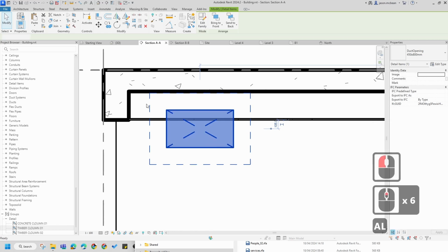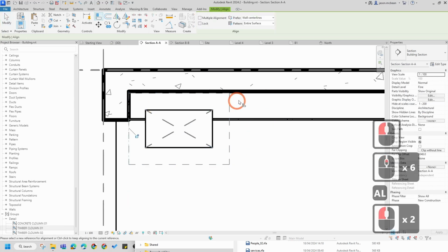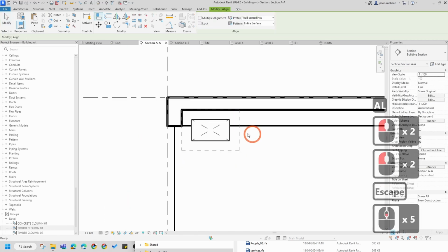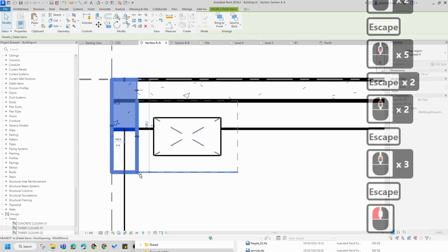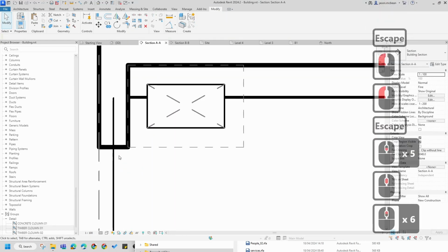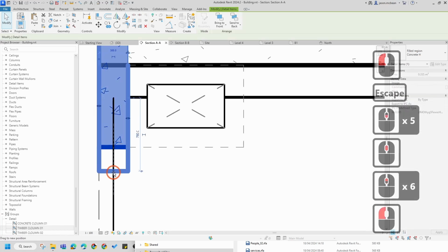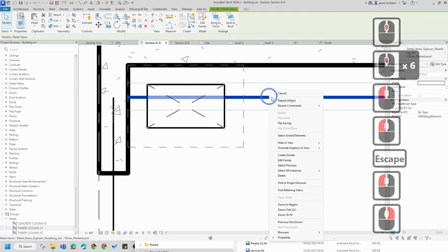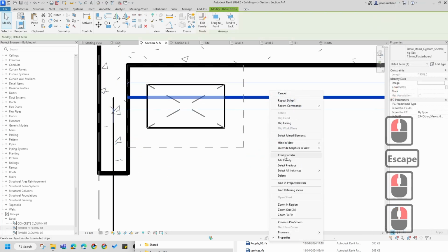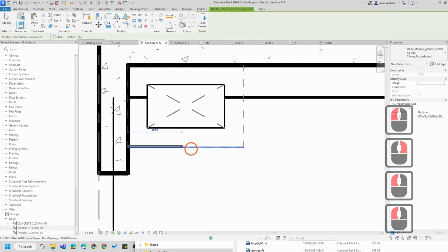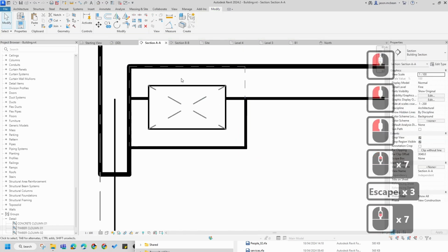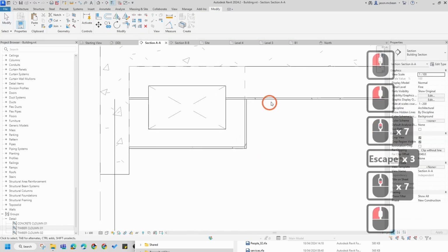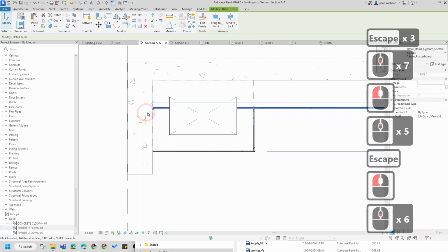So I can go align that to there, align that to there. I've got a duct here, for example, so maybe this downstand beam might have to get thicker, for example, or it might have to come down even more. Create similar. You can use this command to create similar, so maybe here I'll need to put this within the safe zone, so here I can draw in this direction. So that's my, if I go to, then this one will need to stop over here.